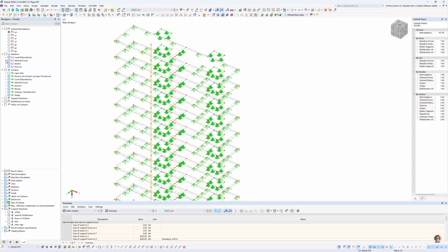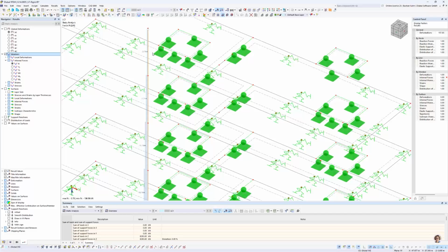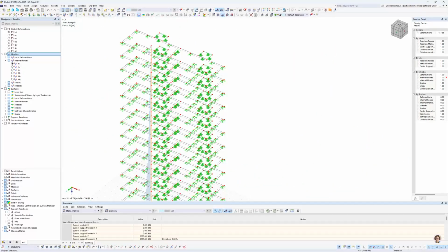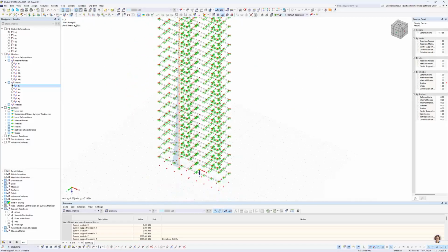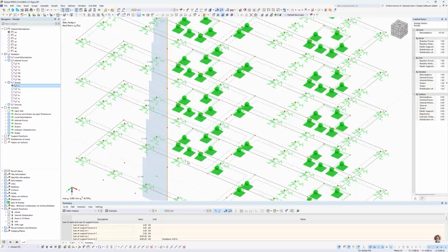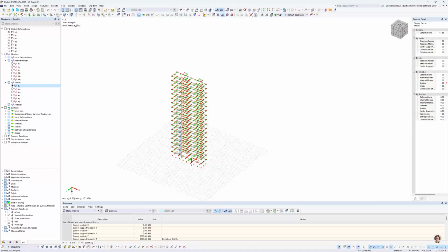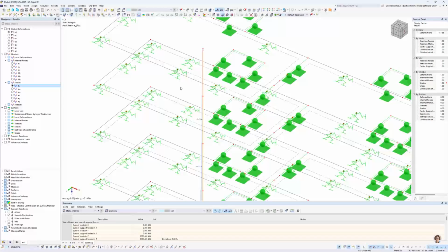I want to take a look at the internal force, the normal force, and you see, okay, that's the same structure. It has the same loading, but it only has a normal force of 3. And why is this effect occurring here? Because it's all calculated in one sudden step. And there you see the strain here is way too low. And that's why this is just a completely wrong result that I got out of it.